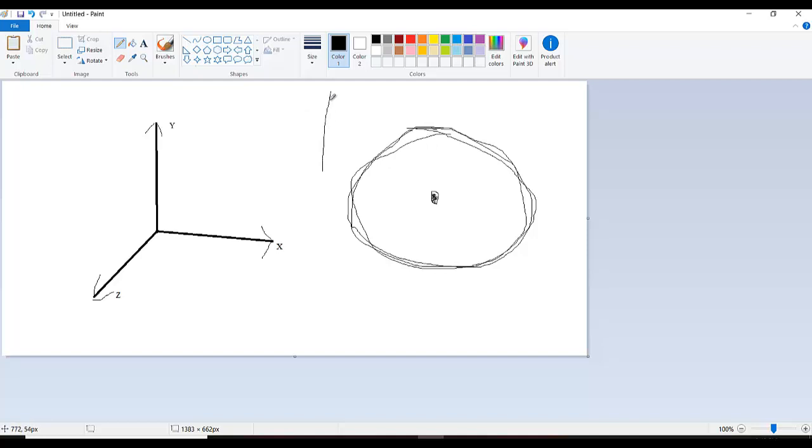First you draw a sketch, like I draw that sketch, and then you can make it revolve around a center point or center axis. Like in Fusion 360 we have these three axes, X, Y and Z. So if you draw a sketch like that, you can make this sketch revolve around this axis or this axis or this Y axis, depending on which plane you draw the sketch on. If you draw the sketch on the XY plane and you want to make a disc, you just draw that sketch and just revolve it.